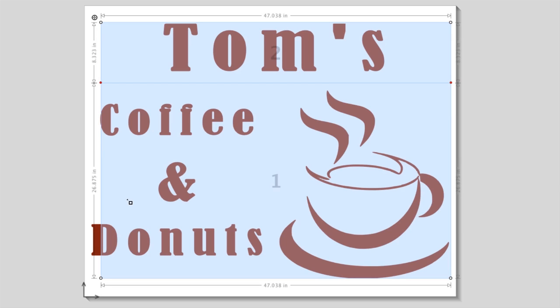Tile lines can also be added to the tile pattern. Sometimes this is needed for a job design that requires smaller tiles for better handling when mounting the graphic onto the substrate. To add tile lines, hover the mouse point over a tile line or tile border, click and drag the mouse, and a new line starts to form. This line can then be dragged to a tile line in the middle, or it can be dragged to the opposite outside tile border, or any tile line in between if there are any.